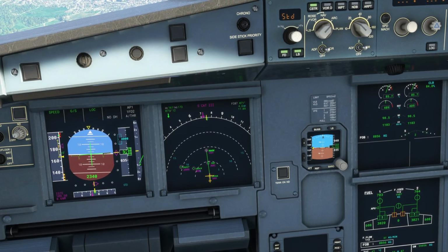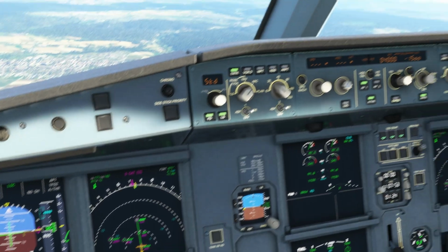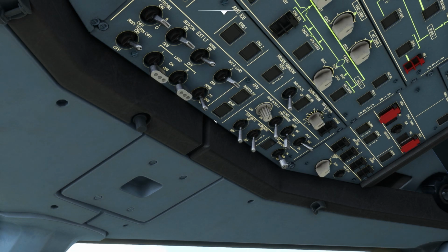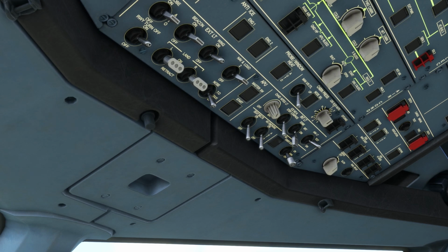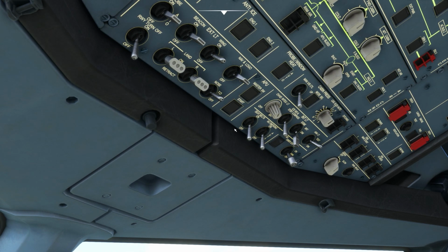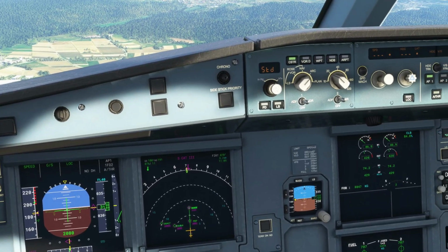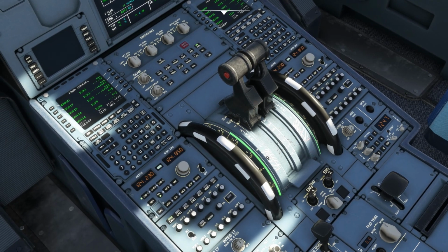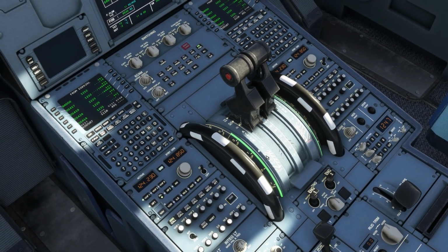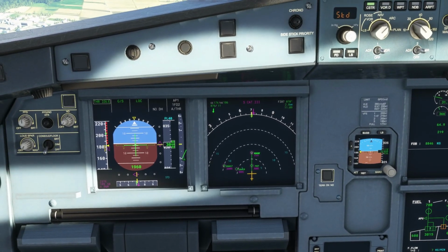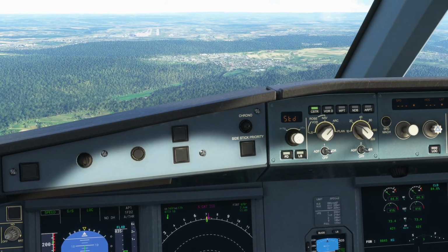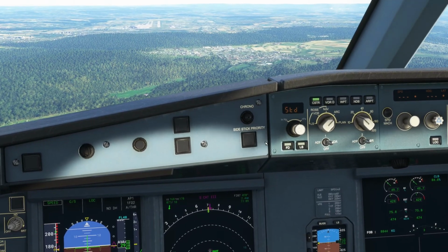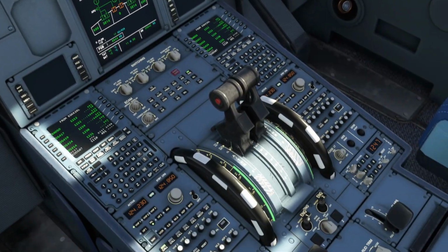Final preparations now for landing. We'll put the landing lights on as well as the taxi lights, and we'll also put the seatbelt and no smoking signs on as well. Cabin crew, prepare for landing. We're about 3.5 nautical miles away from the airport, so time to get the 3rd level of flaps in. That's done now, and we've armed the speed brake. 3,000 feet, 2.8 nautical miles to go. That's the airport, I have that in sight, so flaps can be fully deployed now.